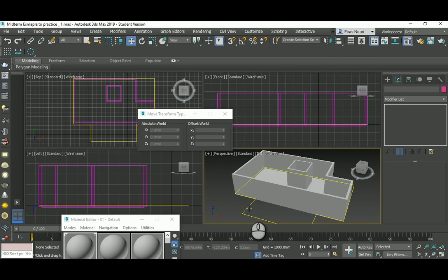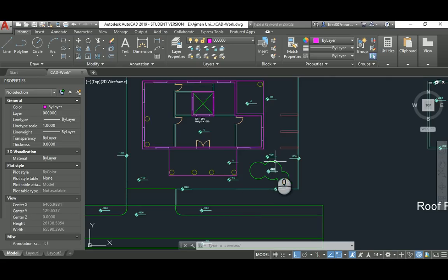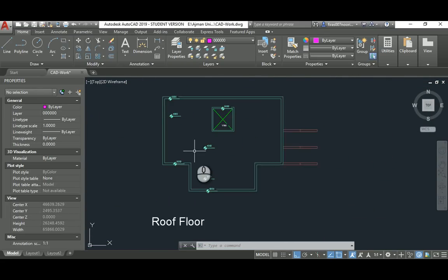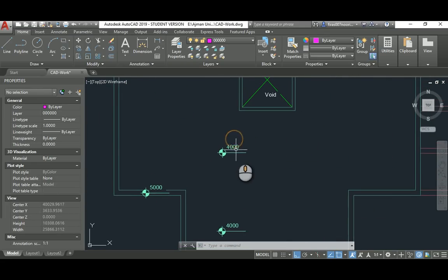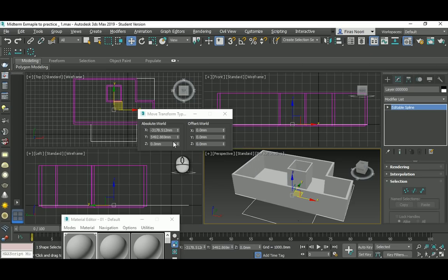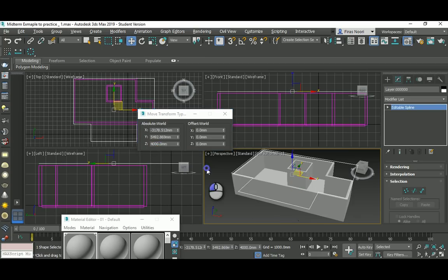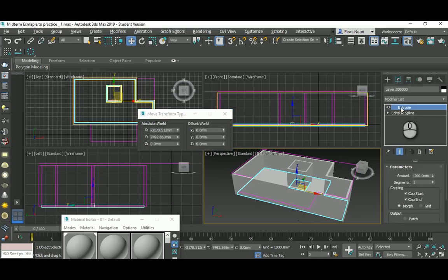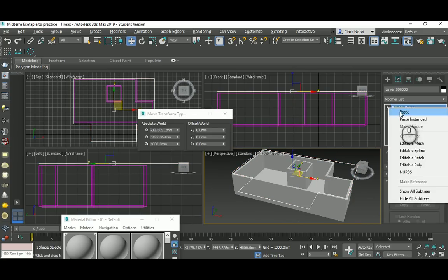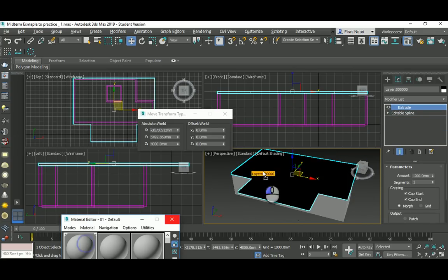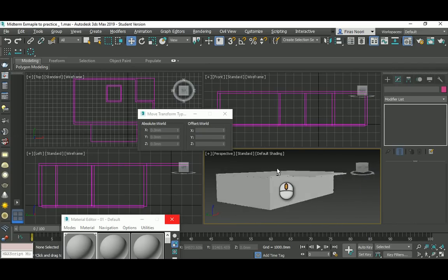And it's here. So again, it's a horizontal surface, so rule number 2, you have to place it exactly as AutoCAD said. It's a 4,000 mil, and that you have to put here 4,000 mil. And the extrude will be also minus 200, so just copy the extrude from here and paste it here. Drop the material on it. That's our roof.